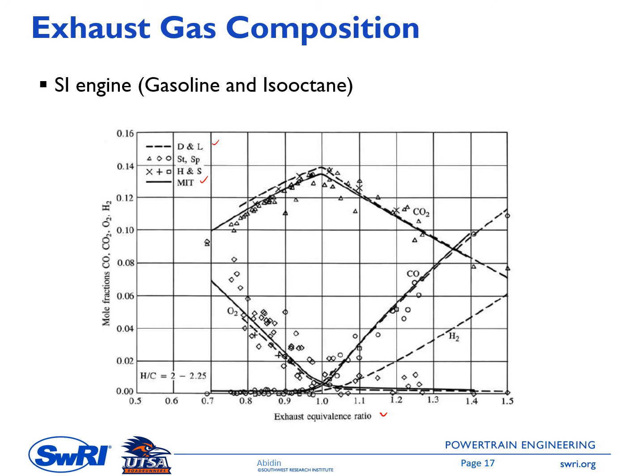Let's take a look first at the CO2. CO2 is maximum when phi equals 1. So it's very important: CO2 is maximum at this point. When we have a lean mixture, meaning it goes to the left, CO2 decreases. Similarly, when we have rich mixture combustion, CO2 also decreases. Next one, looking at oxygen.